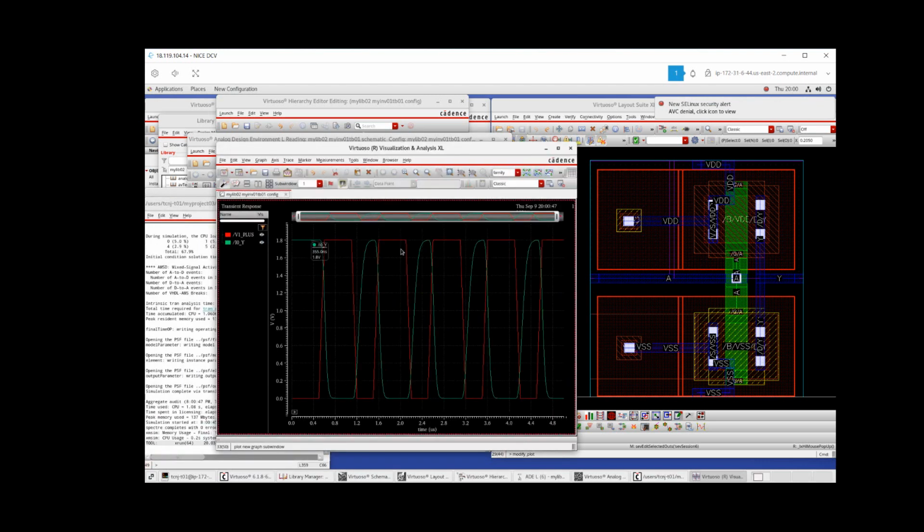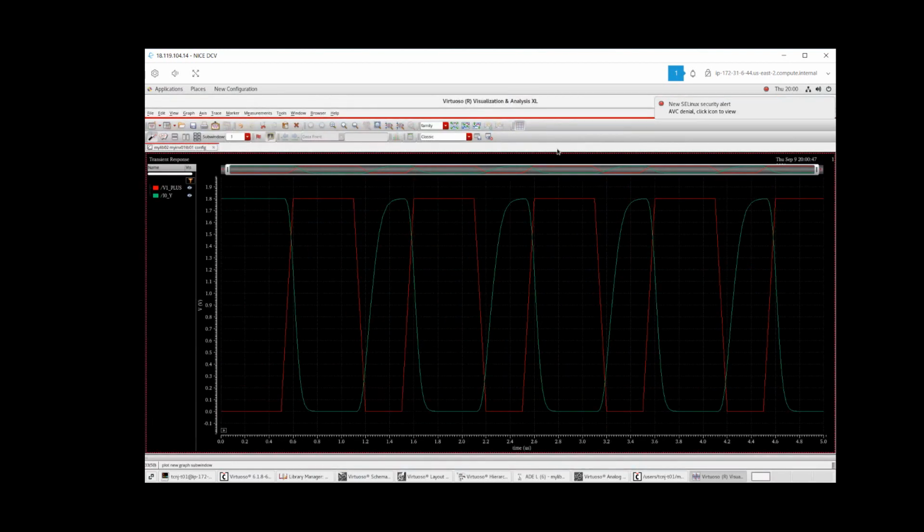And here we have our results. Not much real difference, if you recall, because this is a very small cell, so we wouldn't expect a lot of degradation or a lot of meaningful parasitics. But parasitics are a big deal in bigger cells. So now that we have finished our post layout simulation and made sure that everything still works, we are done. We are just finished, and we can start closing everything.